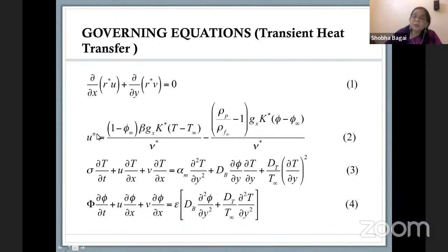We generally work with non-Newtonian flow. Therefore, you will see this parameter n over here. If n is equal to 1, we have the Newtonian flow. And if n is not equal to 1, then we have the non-Newtonian flow. They can either be pseudoplastic or dilatant, and the name has just slipped my mind, it doesn't matter. The third equation arises because of the conservation of energy.